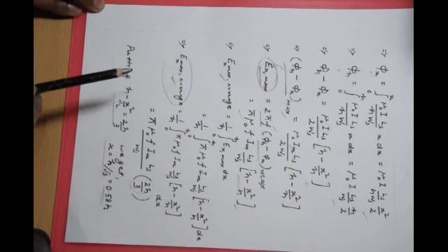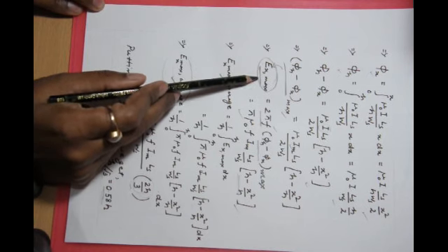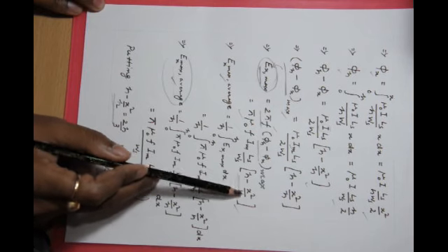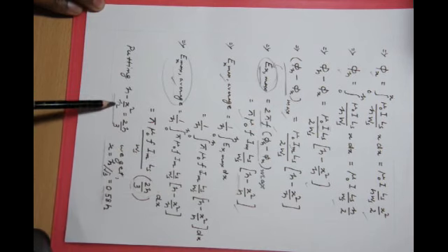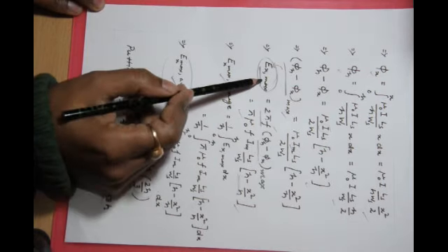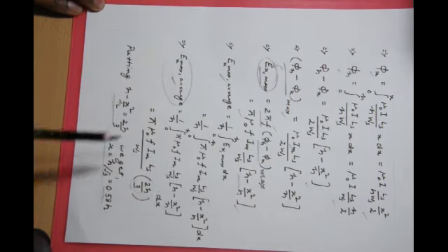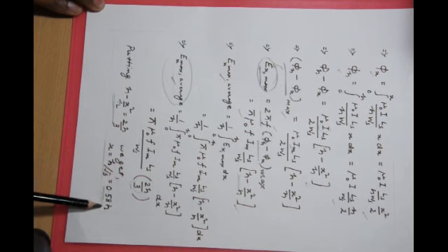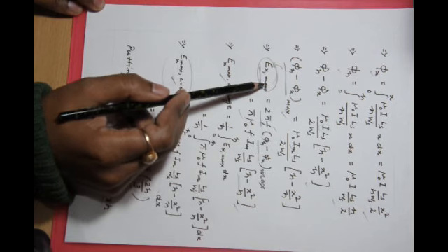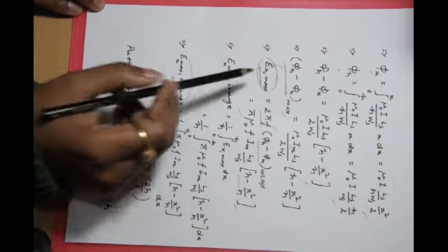Now we need to find out at what height Ex max becomes equal to Ex max average. Simply replace h minus x square by 2h by 3. Equate it, and get the value of x. So Ex max becomes equal to Ex max average at a distance 0.58 h. In other words, at 0.58 h, the difference between Ex max and Ex max average becomes 0.